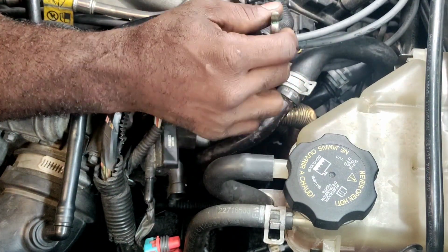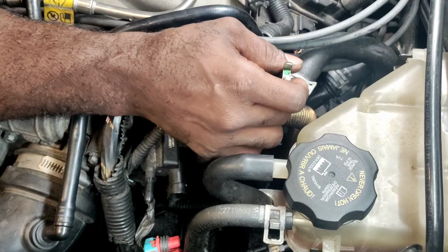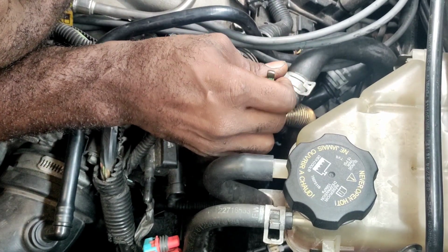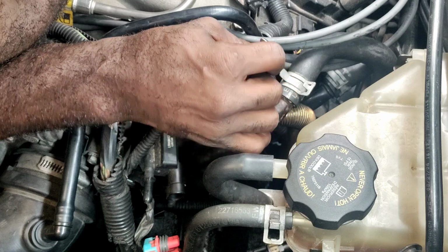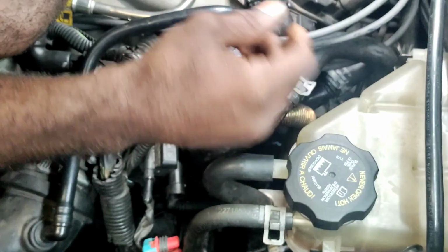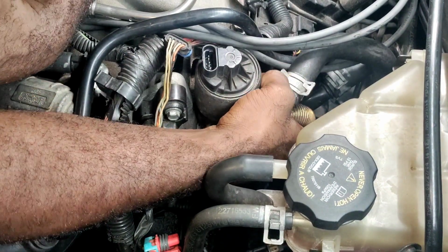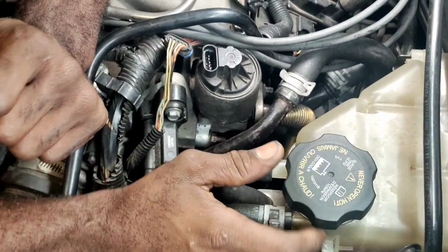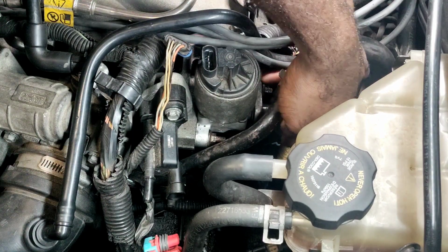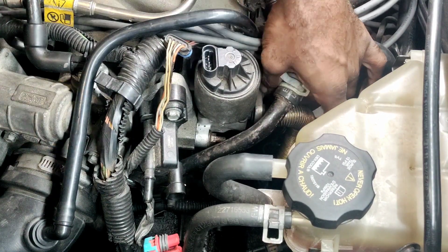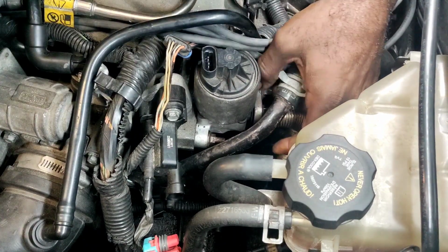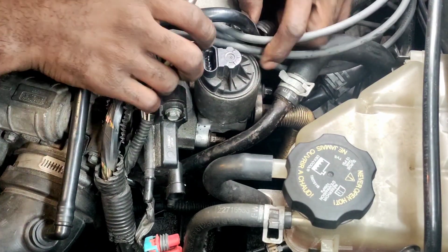Oh, well, this is loose. That'll do it. Did it break? No, threads look like they're... That's interesting. There's always something with a damn GM. Like the threads came off. So in a way, I'm kind of stuck having to replace the EGR valve because I don't like how the threads are going to be.